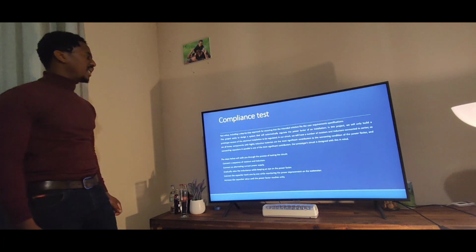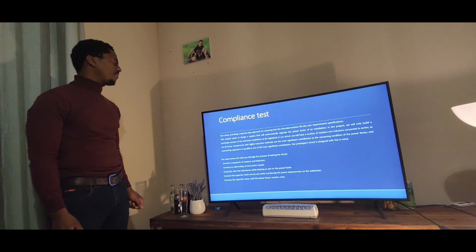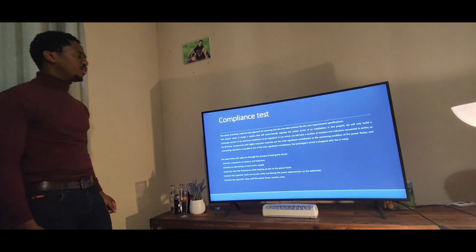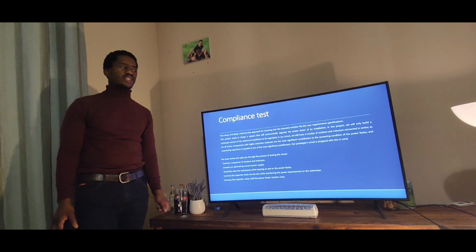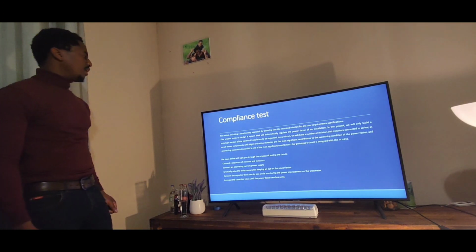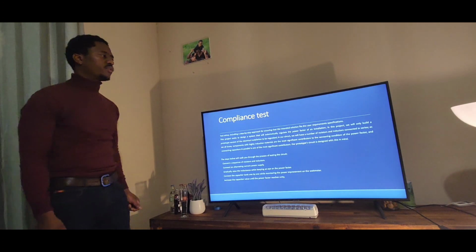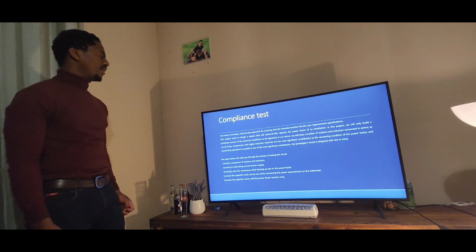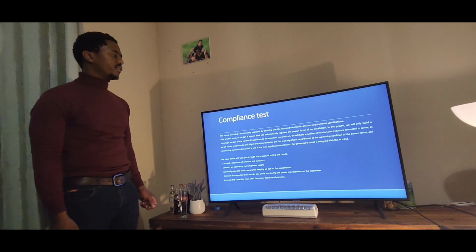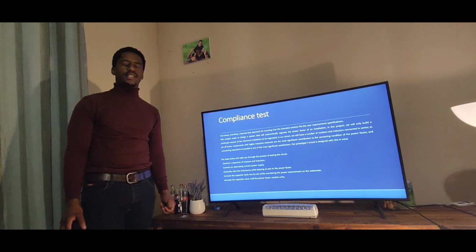This project seeks to design a system that will automatically regulate the power factor of an installation. In this project, we will only build the prototype version of the electrical installation to be regulated in our circuit. We will have a number of resistors and inductors connected in series. As we all know, components with high inductive material are the most significant contributors to the worsening condition of a power factor, and connecting capacitors in parallel is one of the most significant remedies. Our prototype circuit is designed with this in mind.